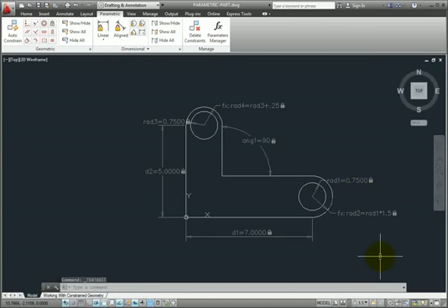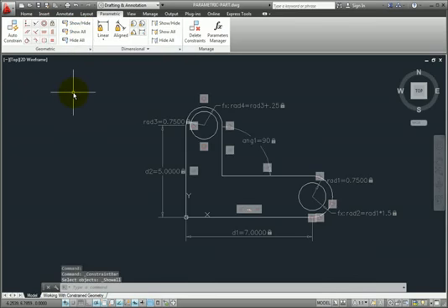As you've just seen, if you change the value of a dimensional constraint, all the constraints on the object are evaluated, and the objects that are affected are updated automatically. Of course, in order for this to work as intended, you must first establish the necessary geometric constraints and then apply dimensional constraints. If geometric constraints hadn't been applied, the lines, arcs, and circles would not have maintained their relationships to each other when the various dimensional constraint values were changed.